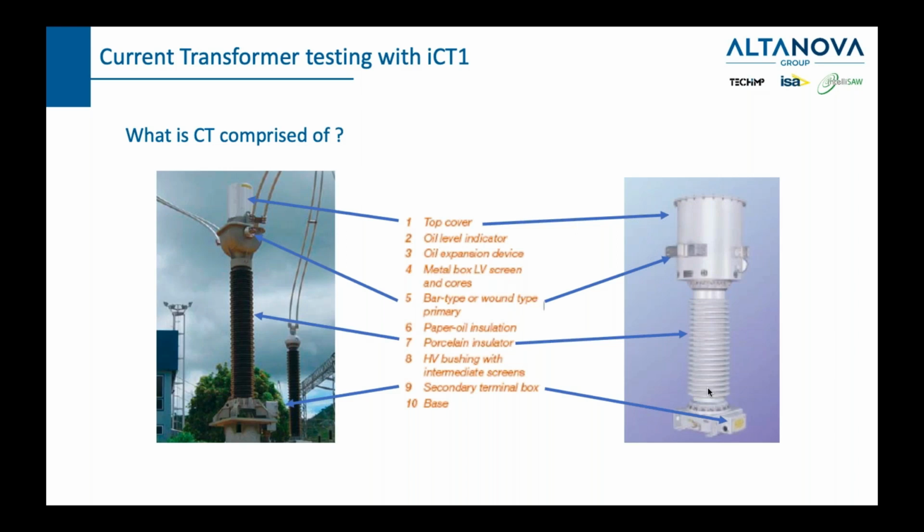As you pass through the substation, we need to know that they're always connected in series, because current transformers, if you want to measure current, need to be connected in series, and that's how we see that connection right here. And of course, the base, which we mentioned before.